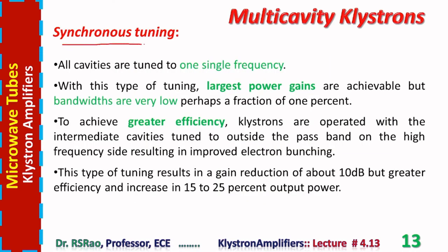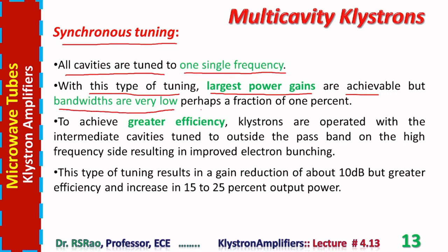Now, a few points regarding tuning of multi-cavity klystrons. All cavities are tuned to one single frequency. Then we say klystron is synchronously tuned. With this type of tuning, largest power gains are achievable, but bandwidths are very low, perhaps a fraction of 1%.